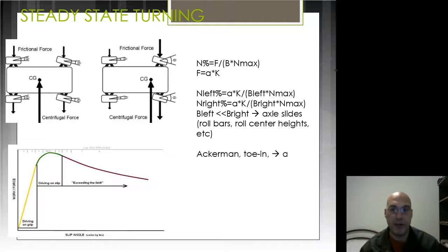Or often using dampers. I had a very good, very fast car setup by stiffening a lot the rear dampers. So I had the rear dampers very stiff. Turning into the turn, it was a front wheel drive car. So when I turned into the turn, as the car rolled, there was a bigger weight transfer in the back. Because the dampers were so stiff, the weight transfer in the back was bigger, and it made the rear slide a bit going into the turn. And this was a very fast setup for a front-wheel drive car.